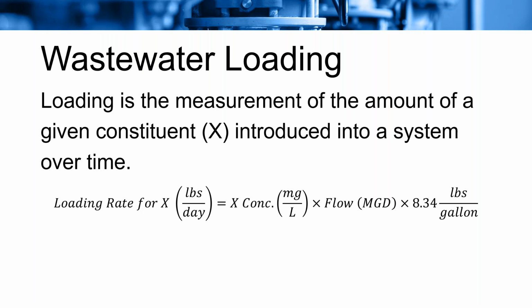And when we talk about loading in wastewater, it's typically the amount of the nutrient and contaminant in pounds per day, but it can also be kilograms per day if you're using SI. And this will apply to such things as BOD, COD, different chemicals. It can be solids, dissolved solids, total solids. So there's lots of different stuff that this can be involved in. And that's where we would use that.